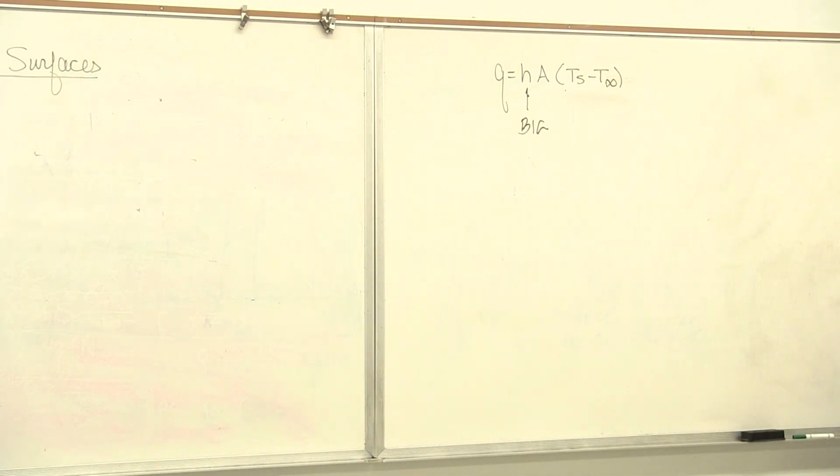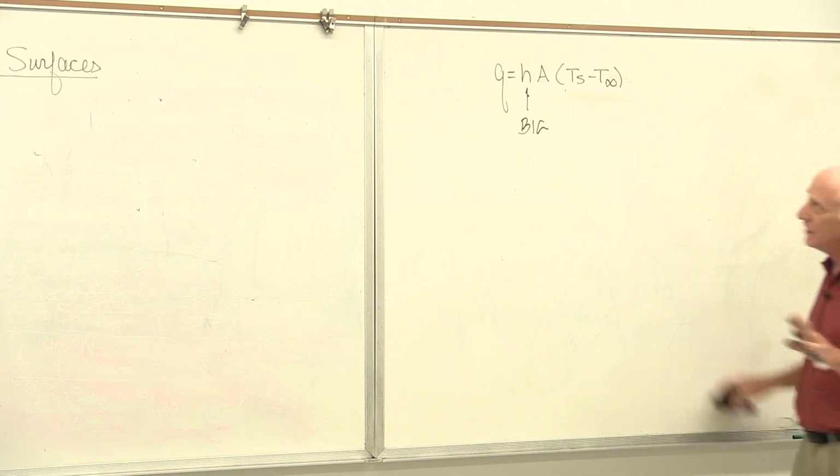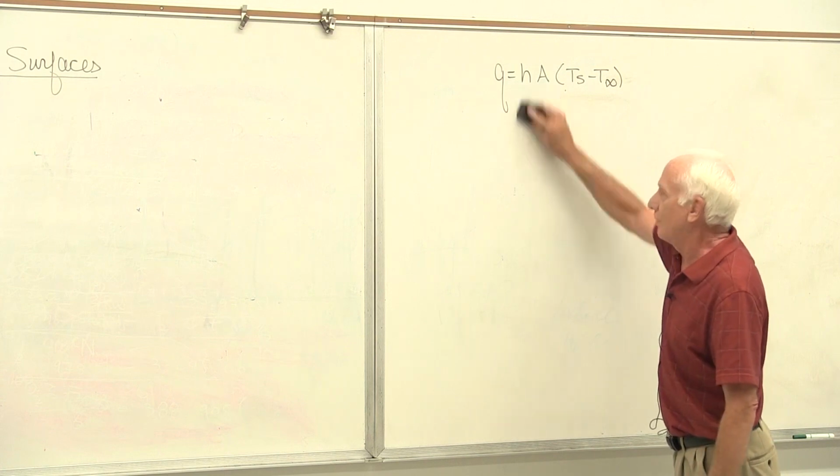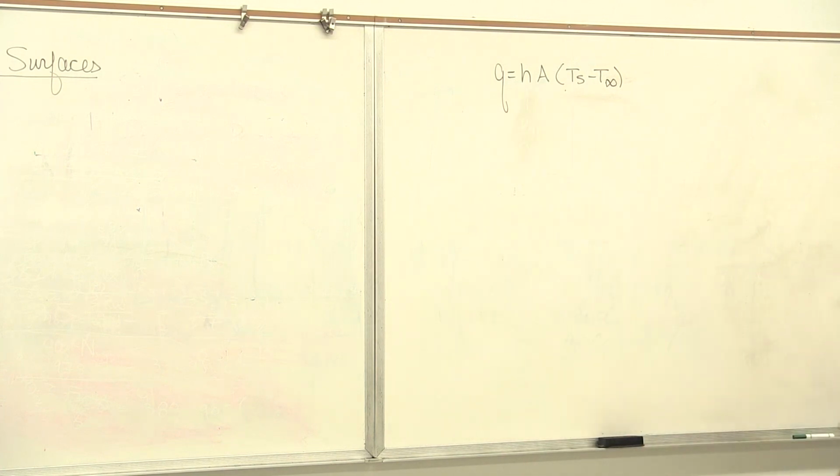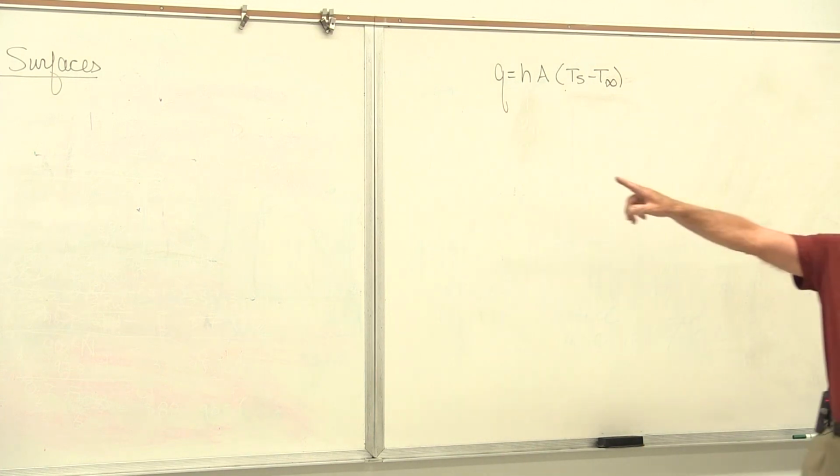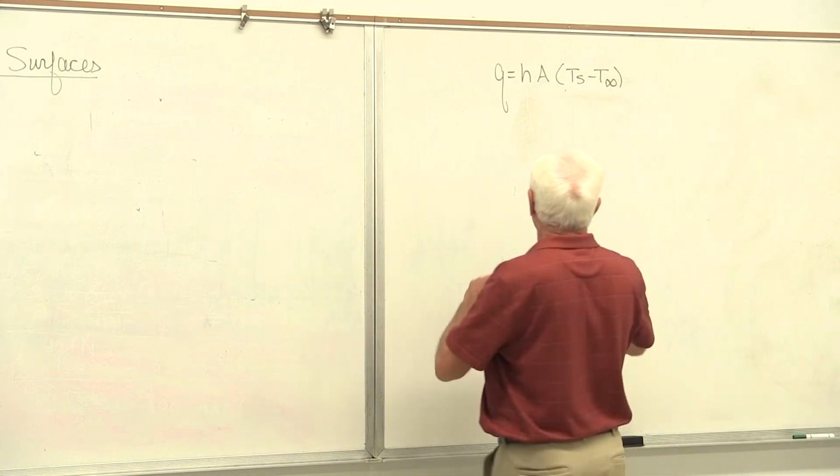You've got this little fan behind your radiator. That's all you got. And it doesn't use much power from the engine. So you don't want to take power out of the engine to drive that guy there. No. So, what are you left with? Area, you got it. That area, extended surfaces. Here's what you say.